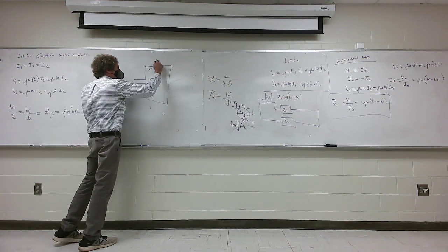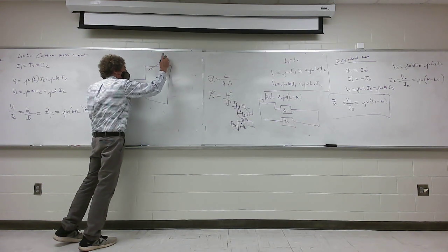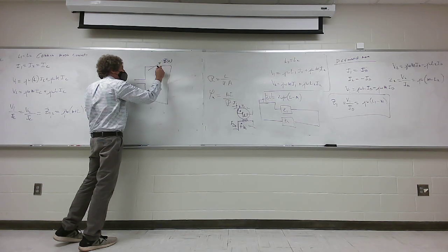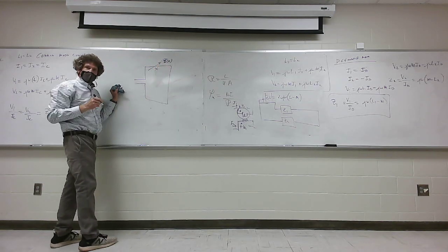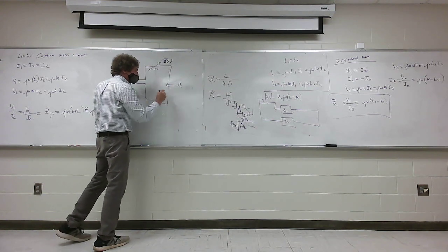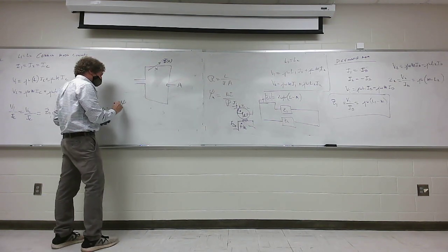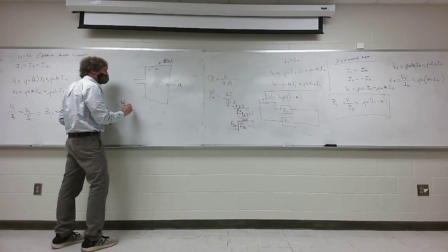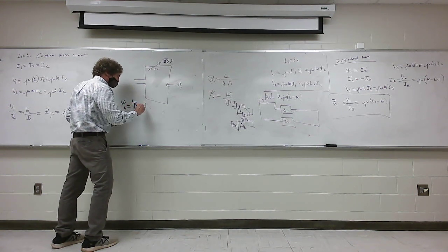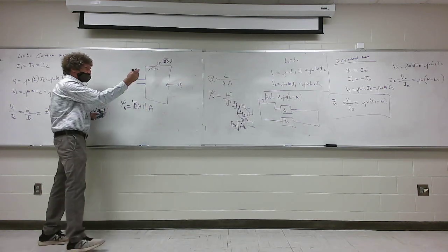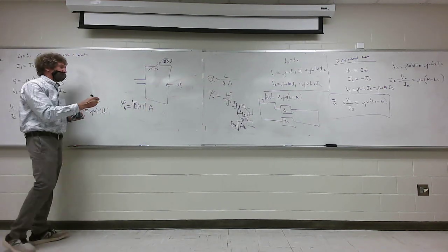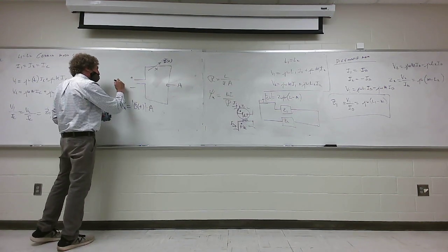And there's a magnetic field that's perpendicular to this, that's a function of time, and it's going into the board. Same magnitude everywhere, right? And if this loop has area A, then the total magnetic flux through that loop is simply equal to the B field magnitude times A, assuming it's perpendicular to that loop. Y'all with me? What's the EMF voltage developed here?